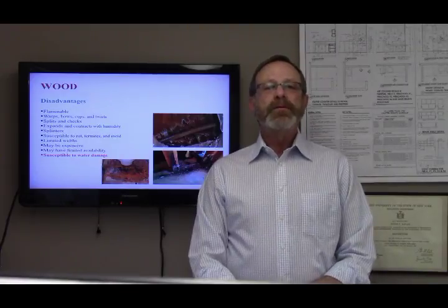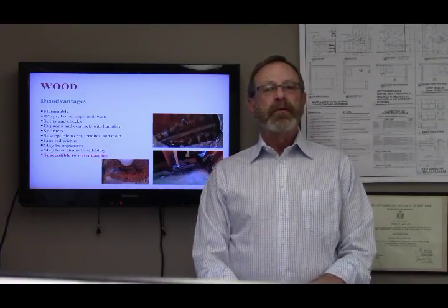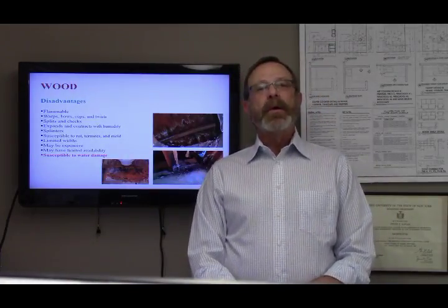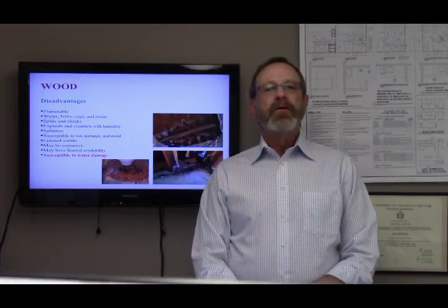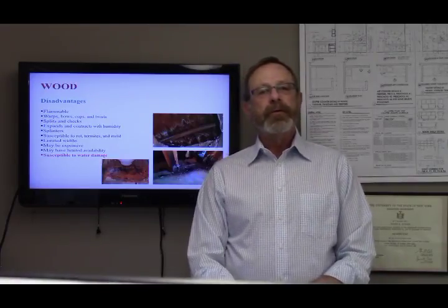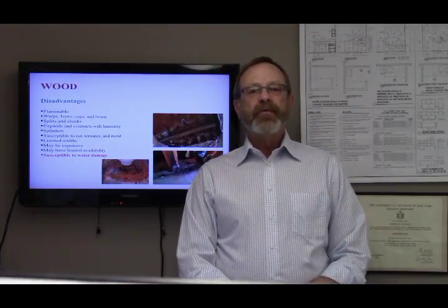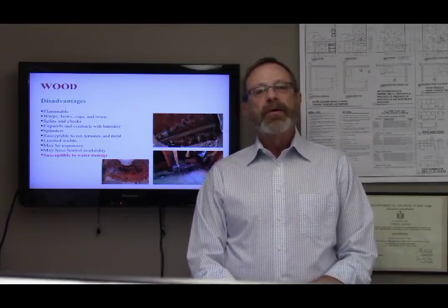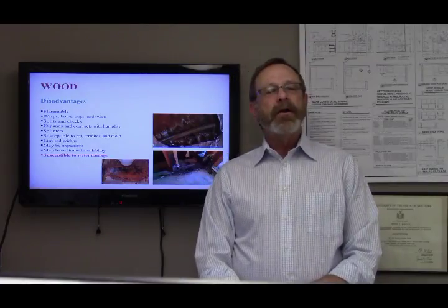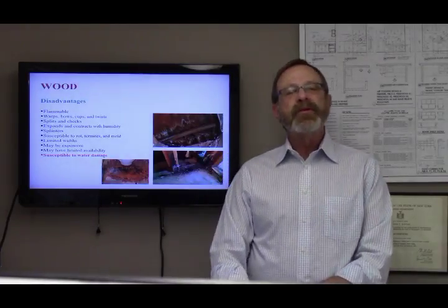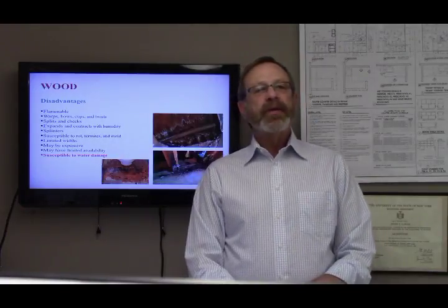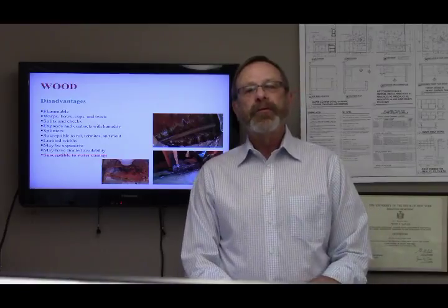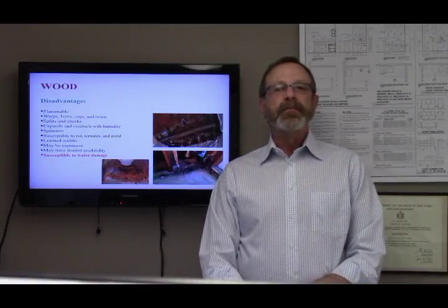Mold and mildew spores are just about everywhere. They are on the wood surfaces and can be transported there by wind and rain. Once in place, all they need is water to start growing and flourishing. Some lumber provides plenty of food for the mold and mildew to grow rapidly. When you see black mold cover wide areas of lumber, usually this happens because the wood got wet and stayed wet while it was being stored. If it's warm and humid, the growth of the mold and mildew can be rapid.